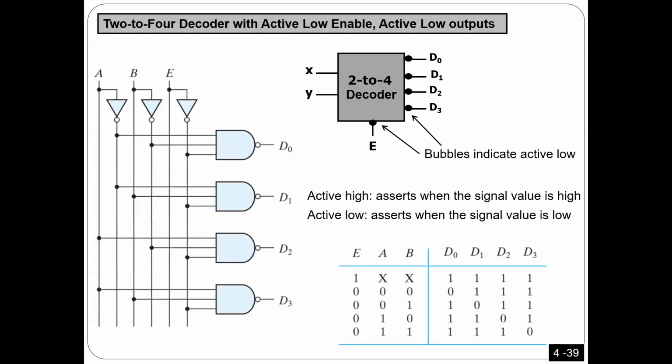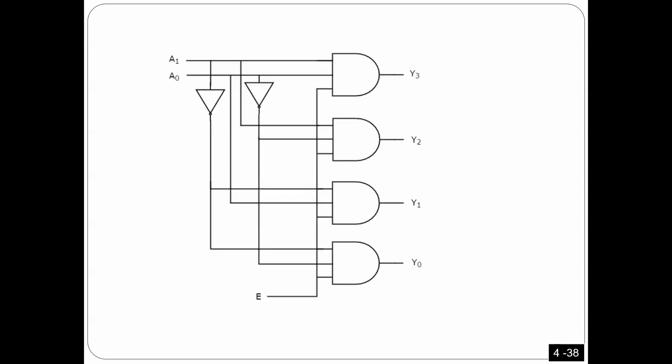Okay. What's really important for me now is, as I told you, when I designed the decoder, the way I designed it is I have one AND gate for every min term. I have one AND gate here for every min term. Only one of them should give 1, and all the others should give 0s. You got what I'm saying? Because the input is going to be only one min term. It cannot be 2 min terms at the same time. It has to be only 1.